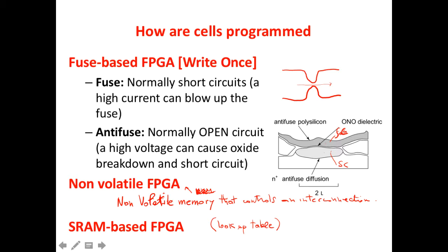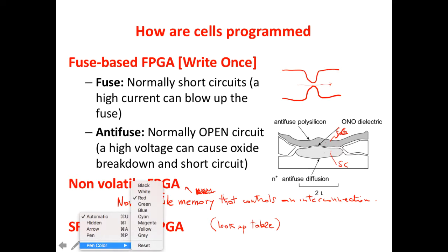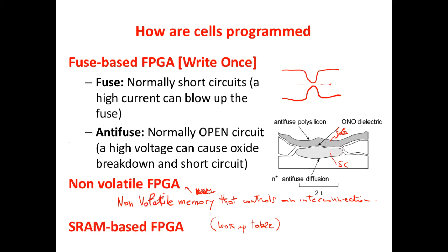And in the typical situation, you have something like this, a sort of view seen from the top. You have a few lines in this direction, a few lines in this other direction, and they typically have no contact, and then you decide when you want to have actually contact by this initial programming phase. Okay? This is also quite common now. For example, most of the Atmel FPGA work with a fuse or an anti-fuse solution. It really depends on the company.